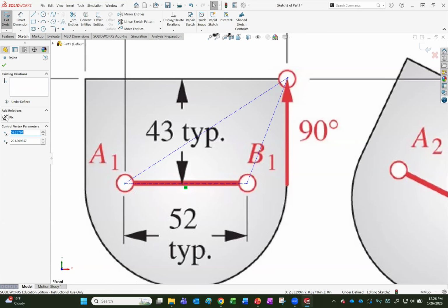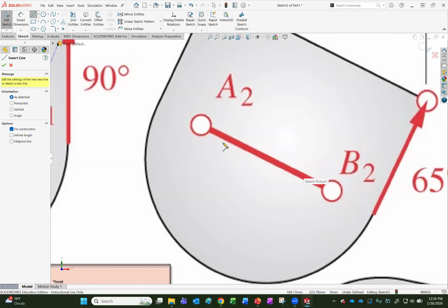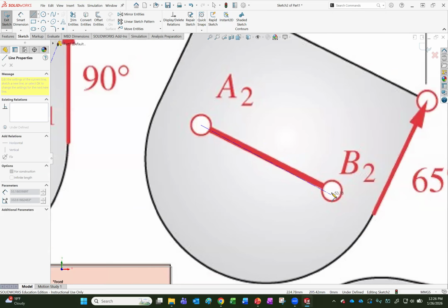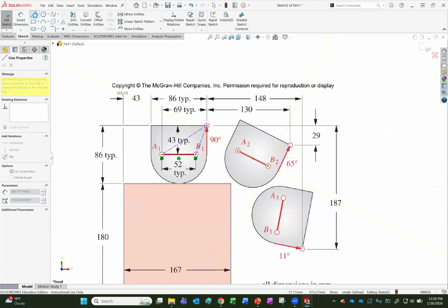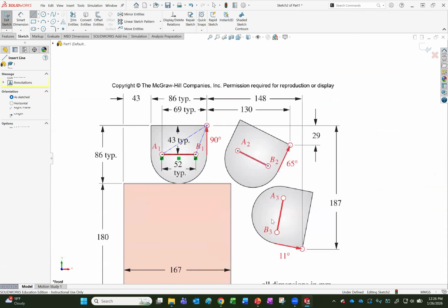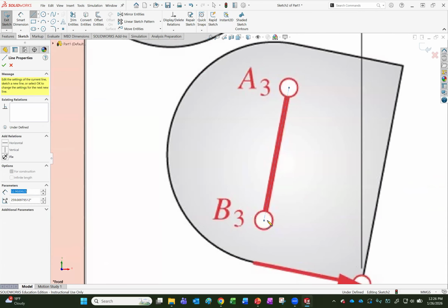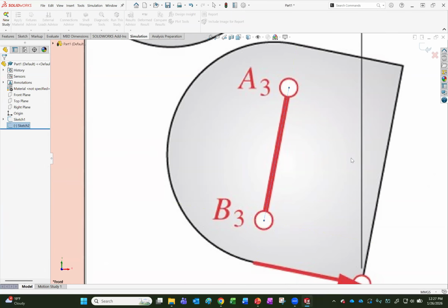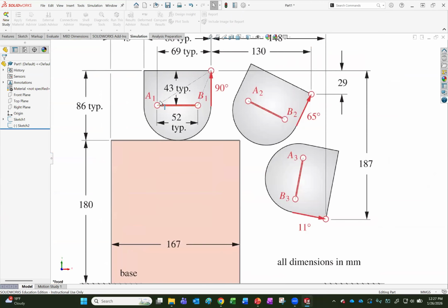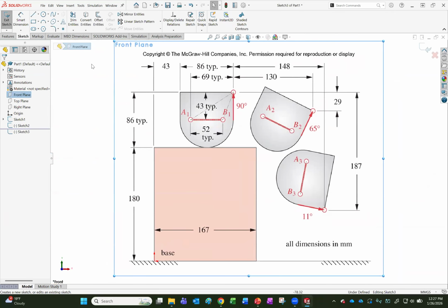So I'm going to set and fix these points right here. Boom, boom. I'm going to fix them, and I'll do this in stages. I think it's better to do this in stages, like as I'm doing it right here, than to try to keep it all in one sketch. Trying to keep it all in one sketch can have things move around a lot more. So I didn't bother with the fixing of the things, because I'm going to keep this as a separate sketch. So I've made the attachment points basically a separate sketch. I think that's easier to do. And now I'm going to do